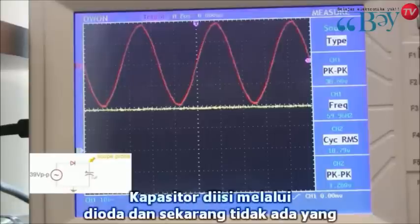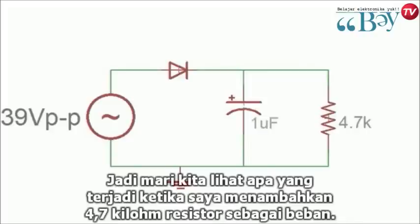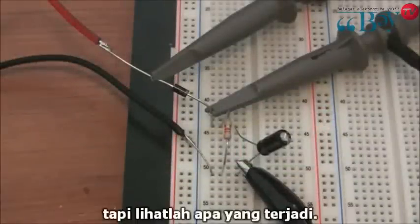Now, unfortunately, the only reason why things look perfect right now is because I haven't put any load on the supply yet. The capacitor got charged up through the diode, and right now there's nothing that would ever drain that capacitor. So, let's see what happens when I add a 4.7 kilo ohm resistor as a load. Ohm's law predicts that this should only be a 4 milliamp load, which is very little, but take a look at what happens.